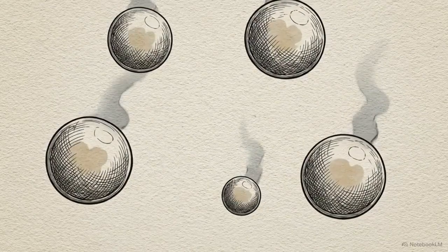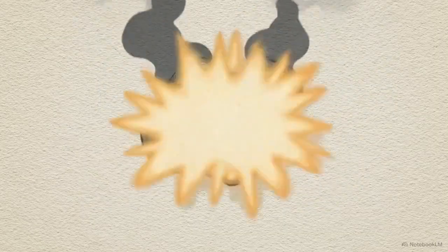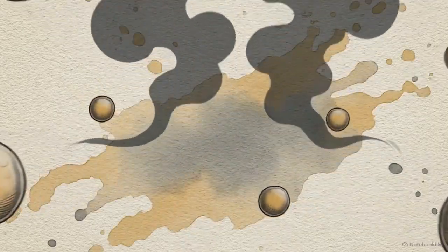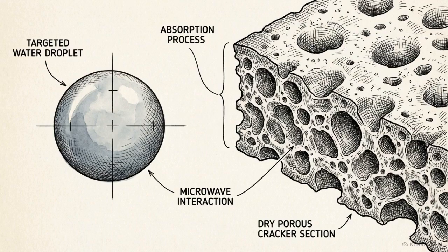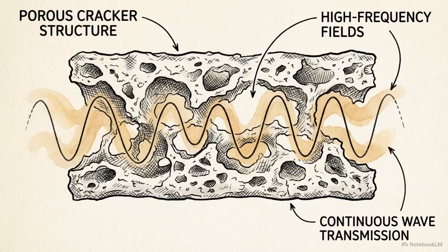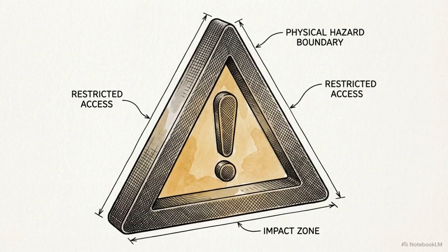This continuous, violent rotation translates directly into internal molecular friction. The friction generates rapid, highly localized heat. Because this method targets specific geometric dipoles, it is strictly dependent on moisture. Without water molecules to manipulate, dielectric heating loses its efficiency, which is why dry foods remain cold in a high-frequency field. This precision targeting also creates physical hazards.